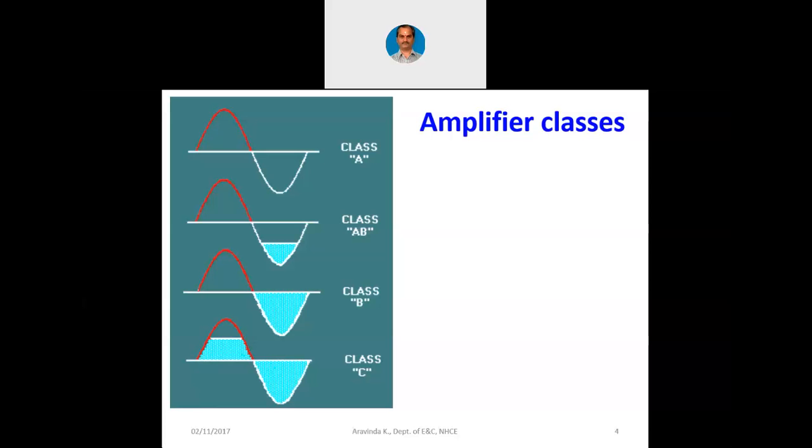Whereas in regular electronics and communication applications, all audio amplifiers are class A, all radio amplifiers are class C. Even in the case of class C, even if the waveform is distorted amplitude wise, it can somehow be reconstructed in some other way at the receiver. Those techniques we will see later on. There are techniques to recover the shape of the waveform at the receiver. We will see those techniques when we discuss the class C amplifier circuit.